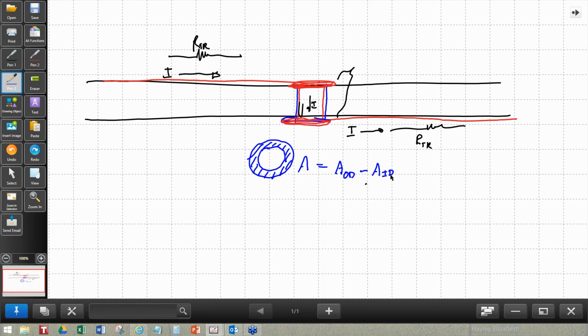If you want to talk about radii, which is what we normally do, let's assume that we have a via. It's pi r squared for the outside minus the inside, right? Or if you wanted to put it in terms of diameters, okay, so we can calculate that area. It's not very hard. What else do we need to know?